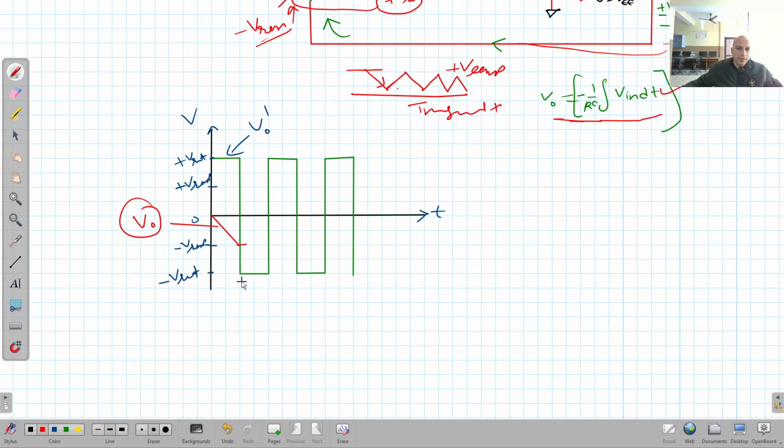Now when it is in negative saturation, the ramp again wants to rise, but now in the positive direction. As it reaches this point, if it wants to go beyond this point, what will be the value? Now the output will be forced to the positive saturation. You can see here, right?